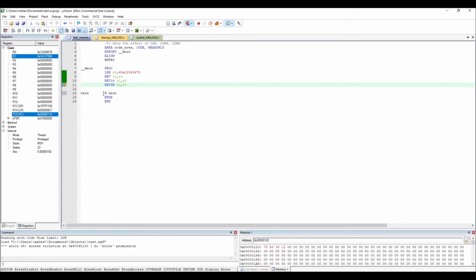That's the idea. Now this is the sign extension one, which means only these bytes will get changed like this, and the other half will be the sign extension of the most significant byte. You can play with it and see. Here, for example, 6 is nothing but 0 1 1 0. So it has 0 as the most significant bit, that's why it became all 0. Okay, so that's the concept.